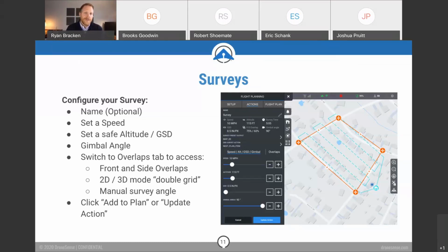If you were to survey everyone on this call today, and there are some true experts actually listening in, which of course is just as scary as having the engineering team watch me do this, you need to really fly a lot in your conditions, in your terrain, with your background, at the times of day that you fly and the weather conditions, and understand what speeds and altitudes and ground sampling distance are going to produce the type of product that you're looking for.